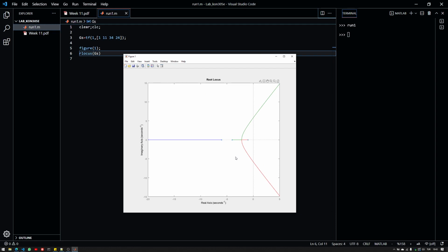Now you have to sketch this, and it should be pretty much straightforward to sketch this root locus plot roughly. If you do not go too much into detail, the first step would be to calculate the poles of the system. Since this is an all-pole system, it doesn't have any zeros, you don't have to calculate them. So since you have only 3 poles, you have to calculate them and place them on the S-domain. Then you have to look for the difference of the numbers of zeros and poles to determine how many poles do not match zeros, so they tend to go to infinity, or in other words, the asymptotes. So you have to calculate the asymptotes and their angles.